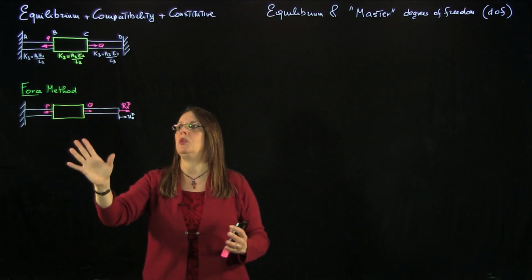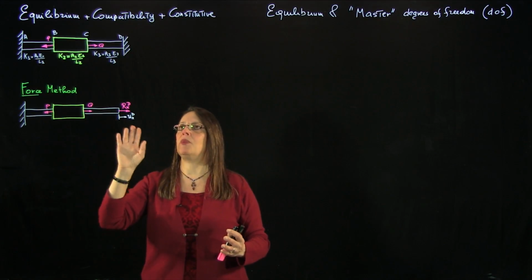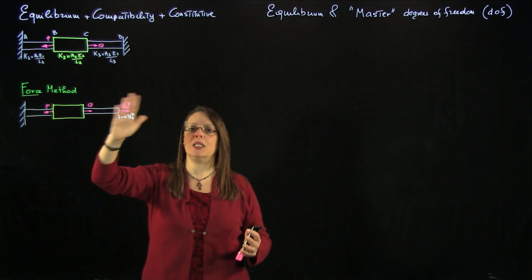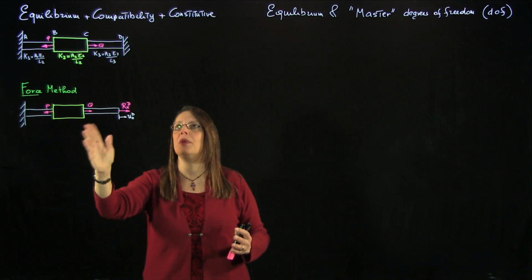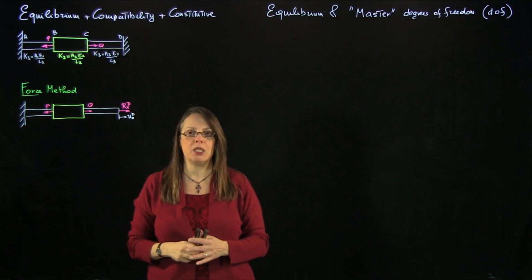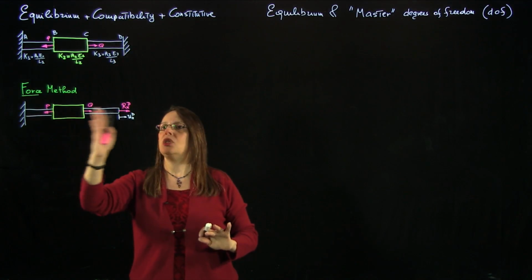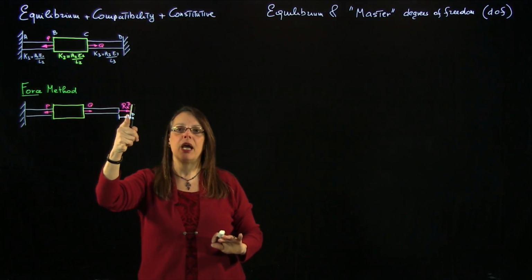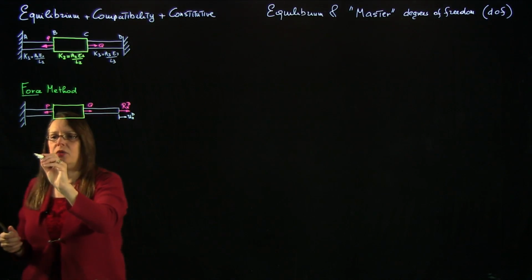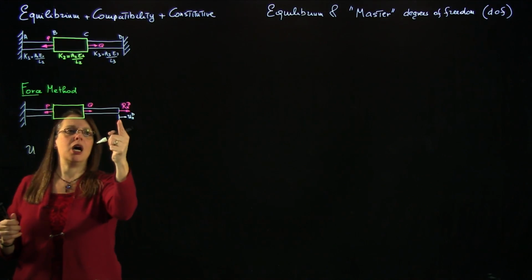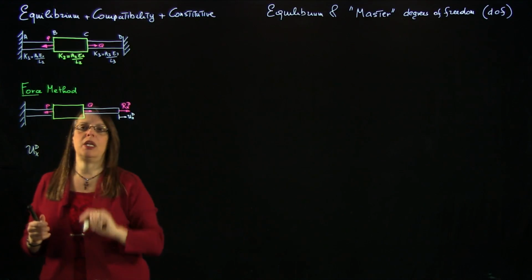So what do we do when we do the force method, and why is it called the force method? It's called the force method because the procedure is that we go from the statically indeterminate system to the companion statically determinate problem by removing the redundant support. So we say, let's get rid of this extra wall. That wall was giving me a redundant reaction Rxd, and then I solve this whole problem and I find what the displacement at the redundant support, uxd, is in terms of the redundant reaction.